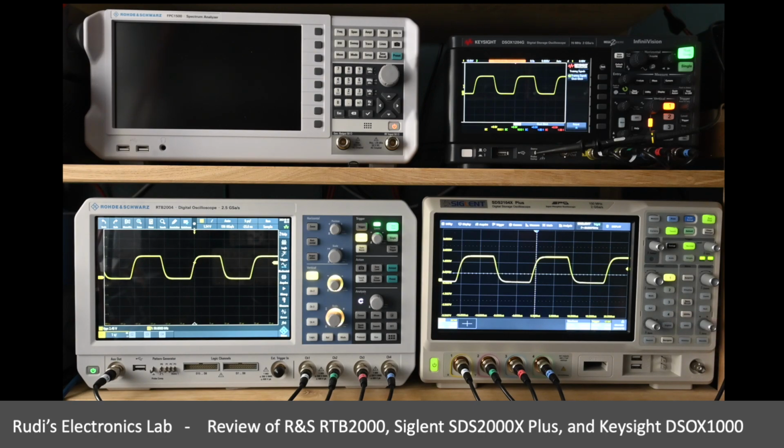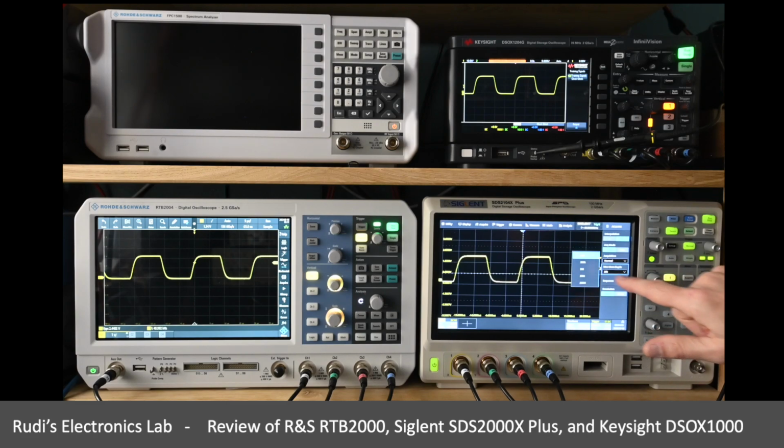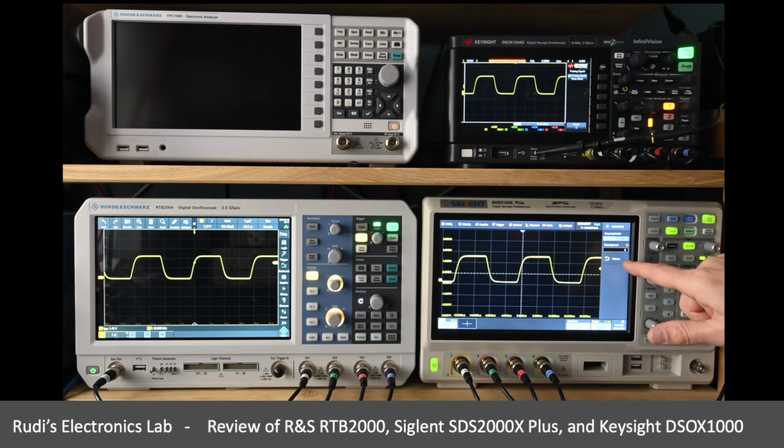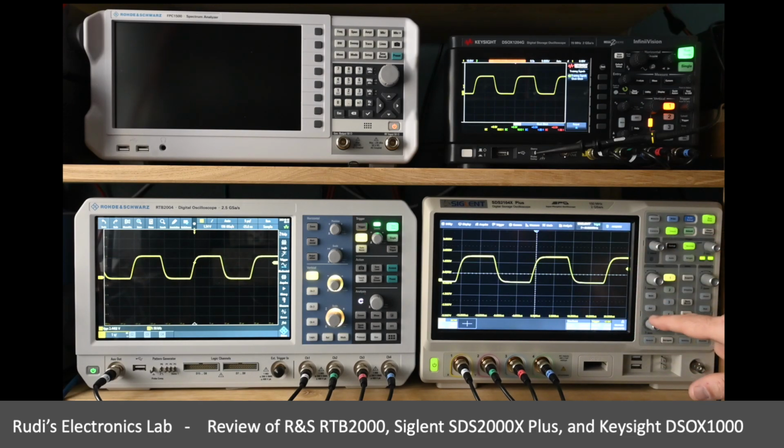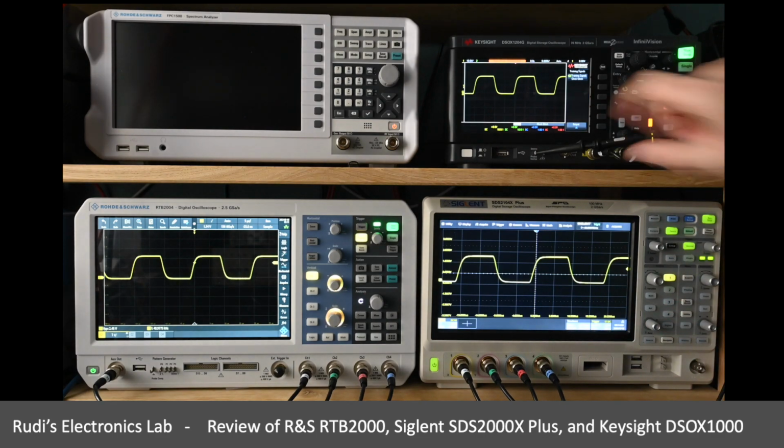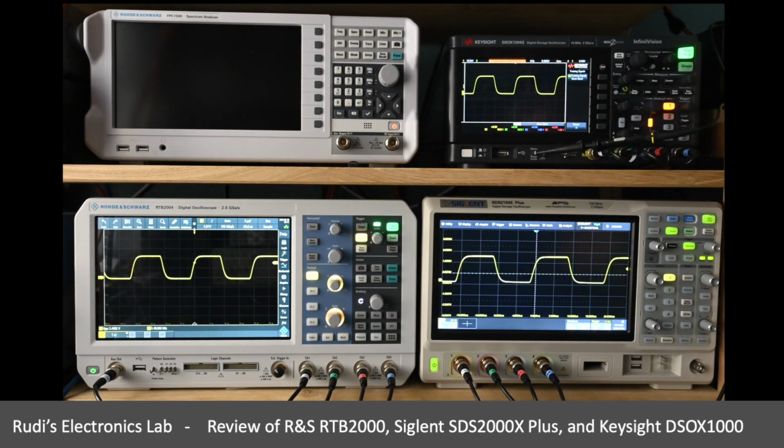On the SDS device, I should be able to go here, acquire menu. I'll also be choosing the shortest one here. When it comes to the sequence mode, that's a little bit more puzzling to me how exactly that's defined, but I've tried all the different settings and now I've chosen the setting which gave me the best results in terms of seeing this on the screen. And the Keysight does not have particular settings in this respect. It is always on its default settings.